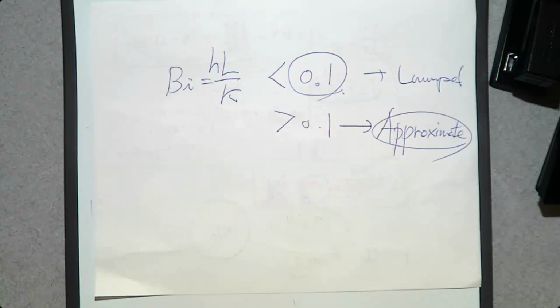Like, what's the range for? That is shown here. So the question is whether there is a temperature distribution in the solid or not, right? So that means the conduction resistance is great and convection resistance is low. So the conduction dominates the heat transfer. Then there is a temperature gradient in the solid. So when the Biot number is small, that means the conduction resistance is pretty small, so you can neglect that. Then the dominant heat transfer is going to be convection. So that was the justification to use a Biot number.